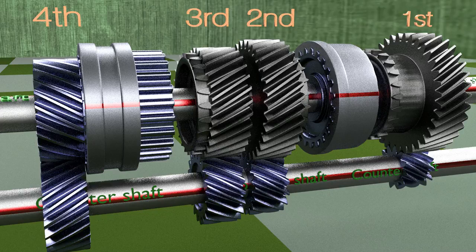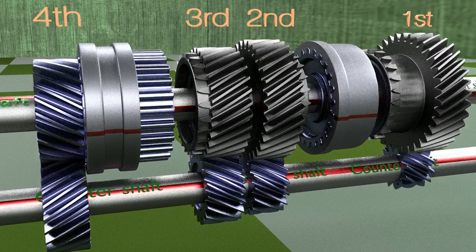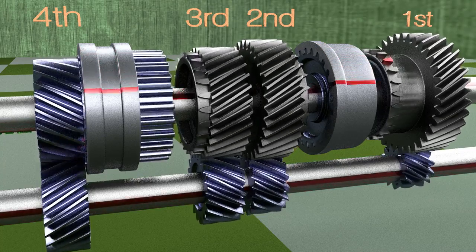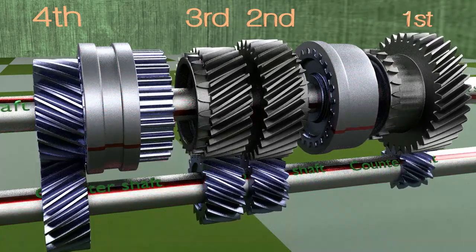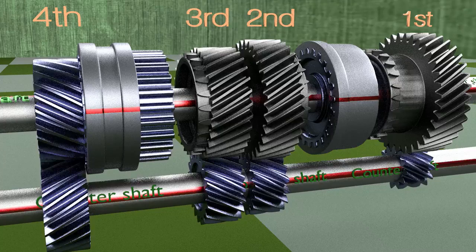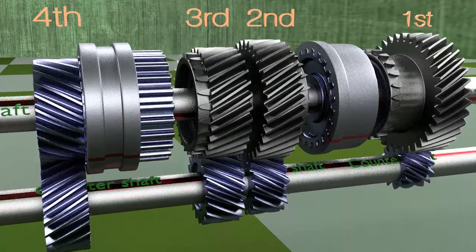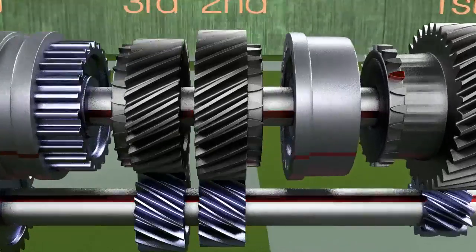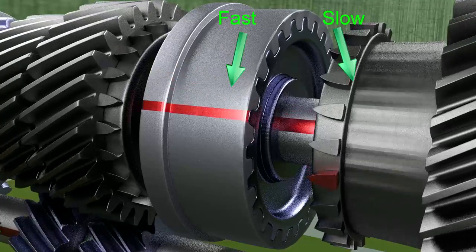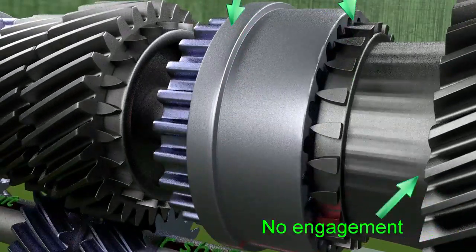But there is a problem. In a constant mesh gearbox, for smooth engagement of the shift sleeve with the gear, it is necessary that the speed of the gear and the shift sleeve must be equal. Suppose we want to shift gear from fourth to first. At this position, the fourth gear is locked to the output shaft and hence the output shaft is rotating at the speed of fourth gear. Therefore, the shift sleeve is rotating much faster than the first gear and as such the shift sleeve cannot be engaged with the first gear smoothly.